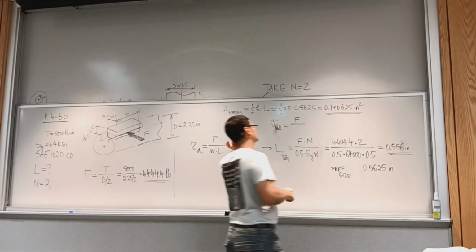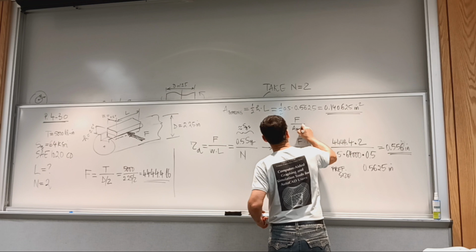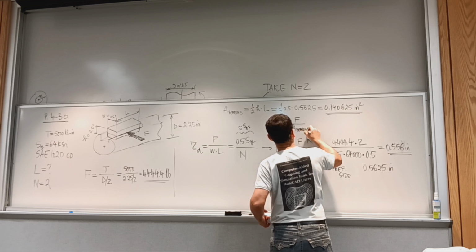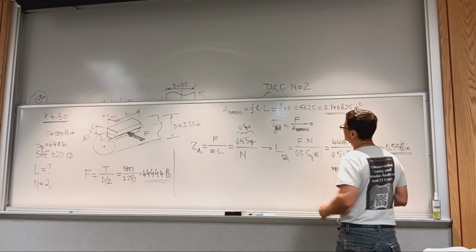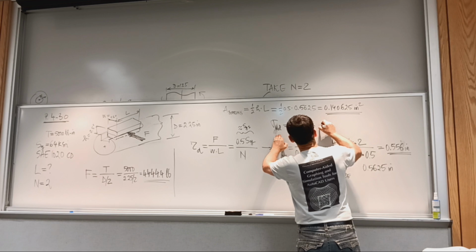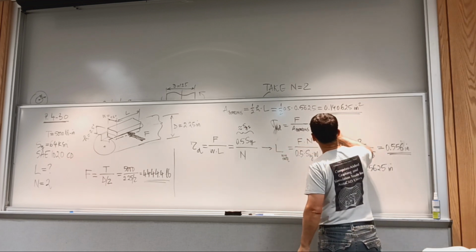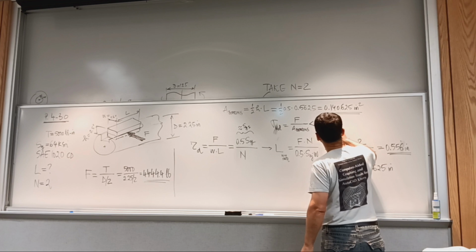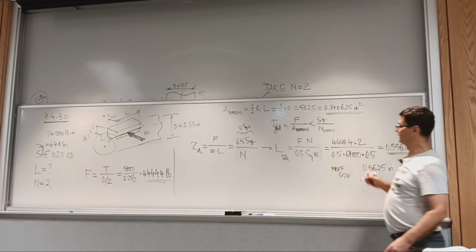But we take the in-between force over the bearing area. And this one has to be less than the yield strength in tension over the design factor, and this will be for bearing. And we check it against recommendations.